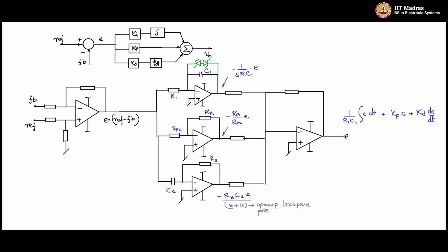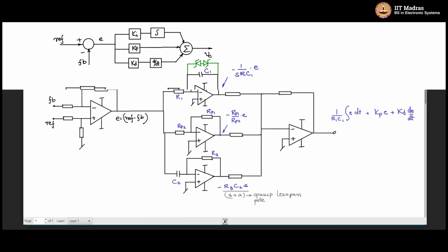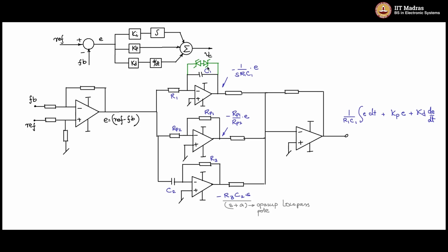So let us say that the output, which is going as a control input to the PWM block or plant control input, has compare limits for the PWM triangle of, let us say, plus minus 5 volts, just like we discussed in the anti-wind-up. I can set the Zener diodes here to be plus minus 5 volts.